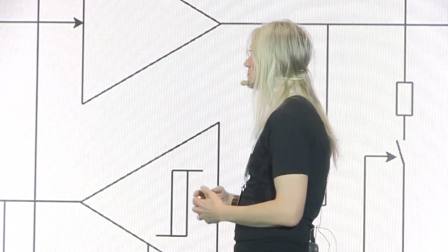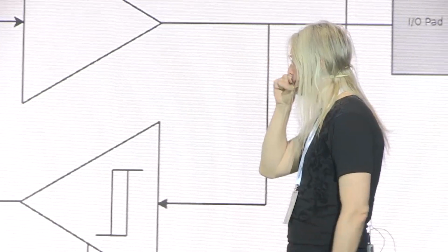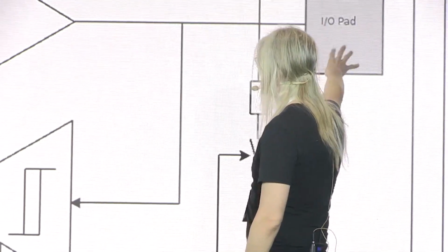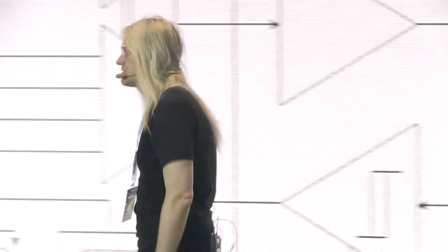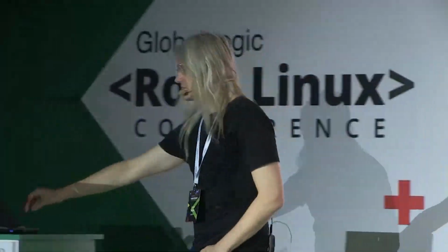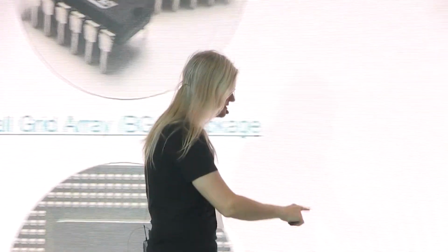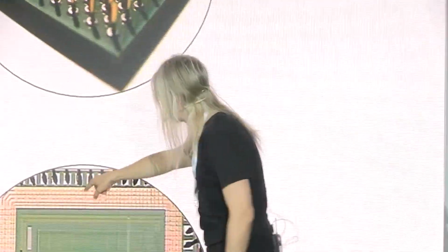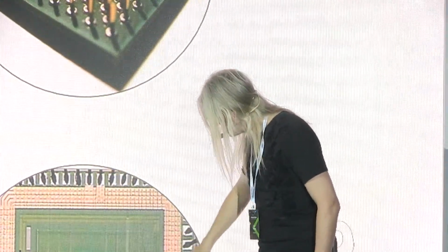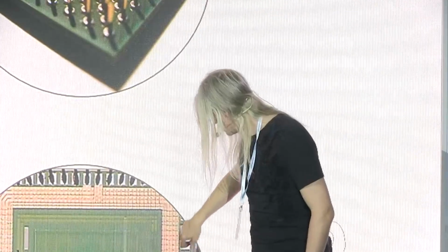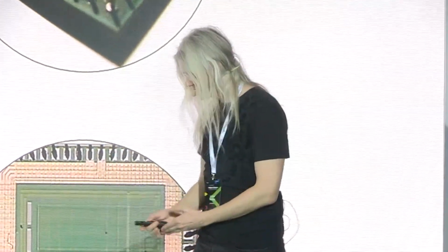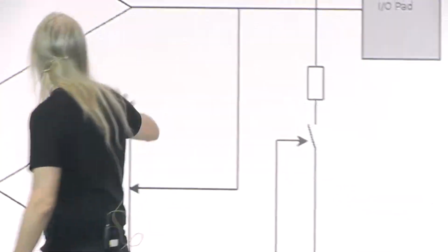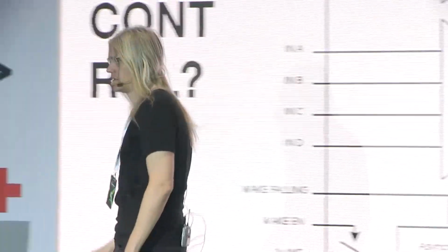And the I/O cell is one specific cell library that deals with driving an input and output to the chip itself. I think I have a picture a little bit later in the presentation. Let's see if it's, yeah, it's there. Look here, here's the chip. There's the pad here, out on the ring. That's the thing that we're driving. And these here around the edges are the I/O cells. They are the transistors driving it. So that's that I/O pad.